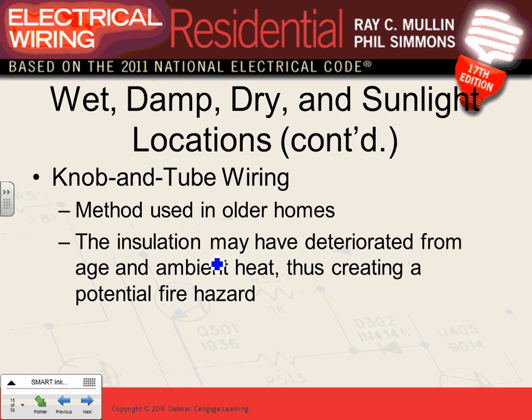Okay, knob and tube. FYI, if you're doing remodeling in an apartment building or a house, you need to understand that knob and tube in the past used to splice. Anybody have wired knob and tube? They spliced with no junction boxes, so you have to be aware of that one. In a lot of applications, if you mess with knob and tube, you basically change the whole wall.